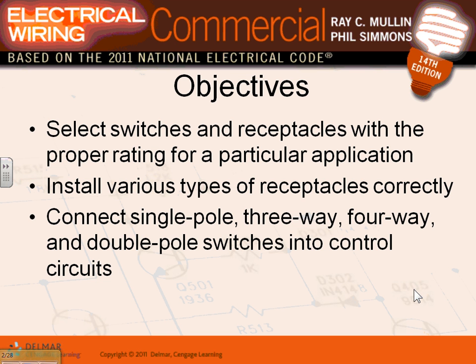It looks exactly like a snap switch. If you look at it, when we go to Halberg and you look at these low voltage switches, 24 volt, they look exactly like this switch, except they are being operated with 24 volts, and they're turning on and off a relay instead of turning on and off a lighting fixture like this. They turn on and off a relay coil, which in turn drives a fixture through contacts to open and close. Now we're getting into more of a lighting control system.